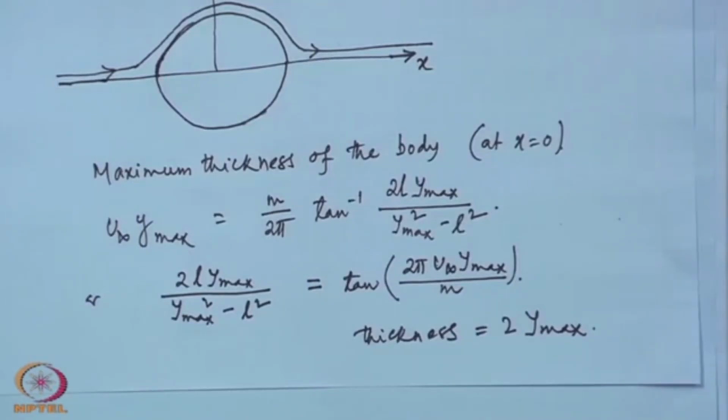So, these are the formula which will be used to find eventually m, the value of source strength. Remember, in a practical problem, let us say that you are given an oval and you have to find the flow. You know this much, that the flow over an oval is superposition of a uniform stream plus a source and sink pair of equal strength.